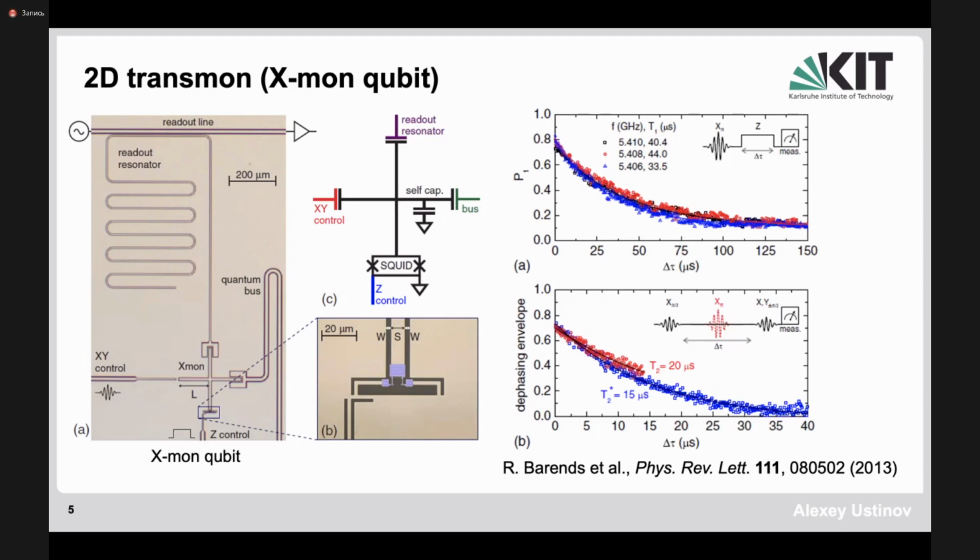And the resonator in turn is coupled to the transmission line, where you send a microwave tone, and then at the frequency of the resonator, one observes a dip. And this dip shifts in frequency if the qubit state is changed from 0 to 1. So if you go from the ground state to the first excited state, this allows you to read out the qubits.